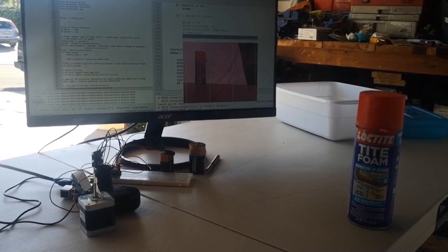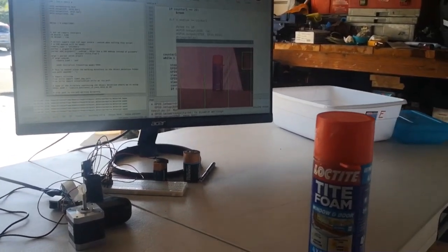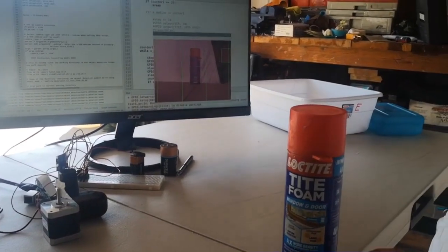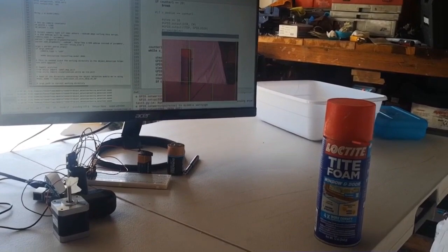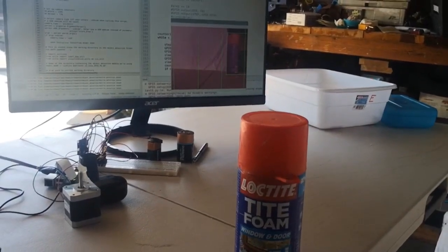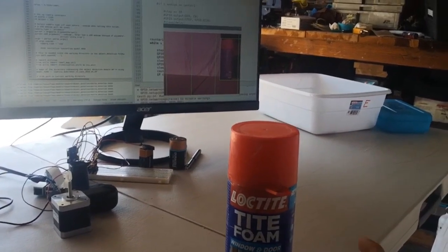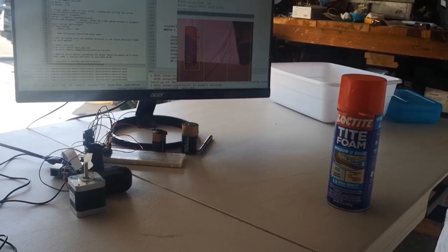As shown in the video, the stepper motor rotates based on the location of the object to allow the motor to adjust itself until the red object is in between the two boundary conditions that we created. If the object is located on the right of the camera, then the motor rotates clockwise to center itself. If it is on the left side of the camera, then the motor rotates counterclockwise to center itself.